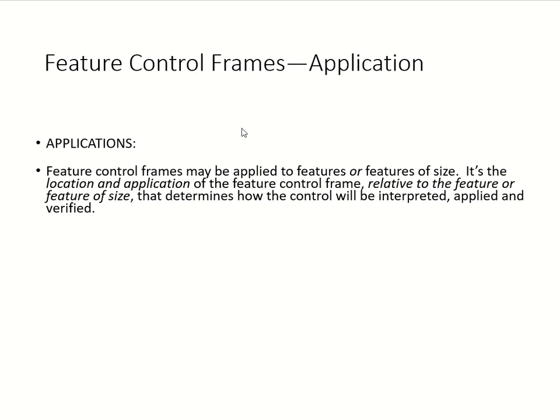We're learning how to write drawing specification tolerances, and we use a box, which we call a control frame. It's just a little table giving you everything you need to know about that feature, the size of the feature, and the tolerance. There's a way that you put it in each cell. What information are you going to put? And they come in an order.